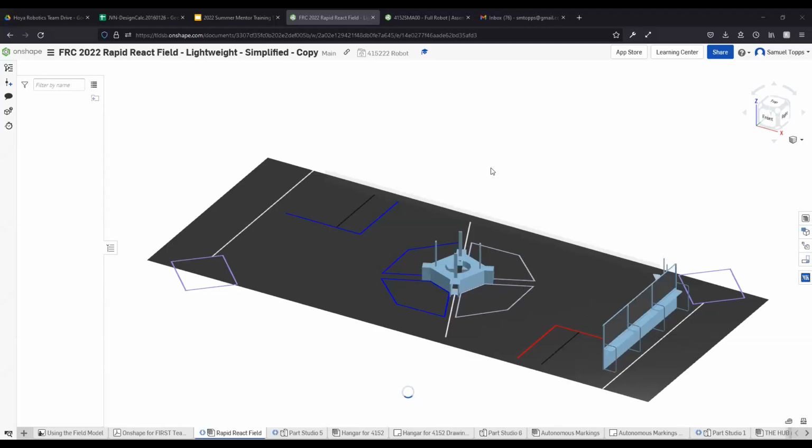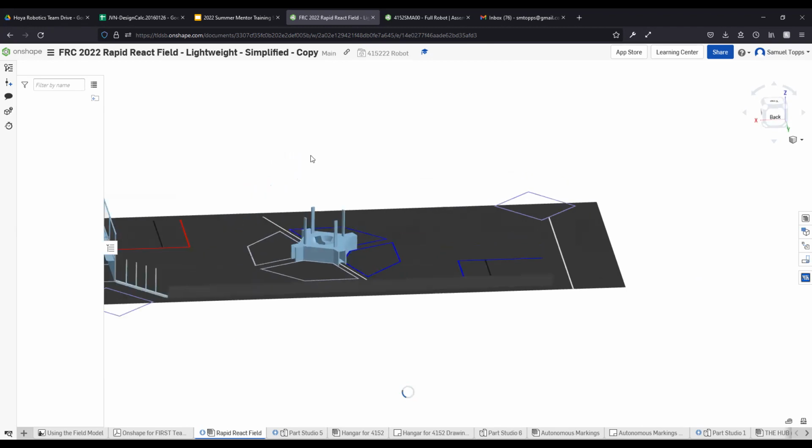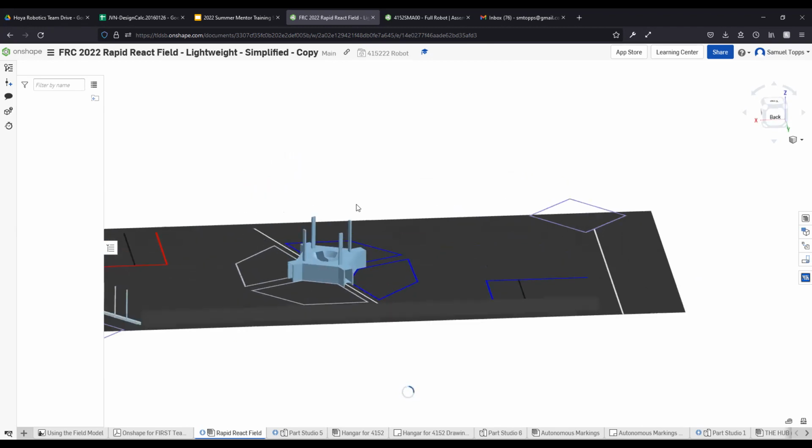Yeah, center of gravity. So while he's pulling it up, in Deep Space, for example, our robot went full tilt in one event, and the driver hit the brakes, and we ended up tipping our robot, and for the rest of the match we were out of commission. So that was a bit of an issue. And so we're really conscious of center of gravity now, so that the lower it is, the less chance you're going to tip over, but it can also help with hanging and stuff.